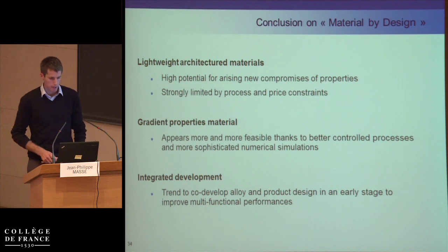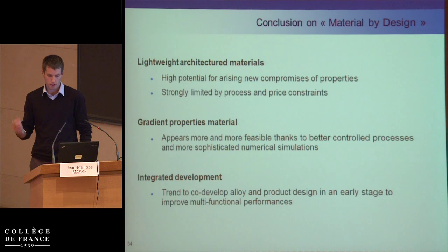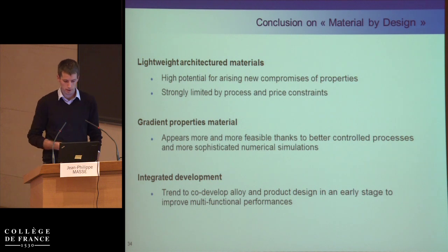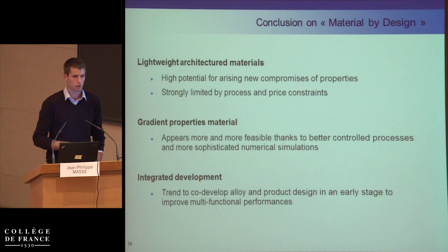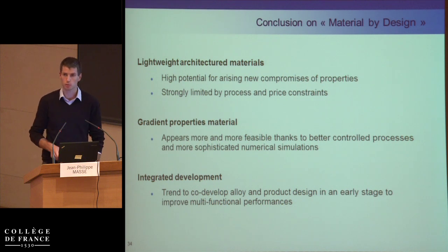So my conclusion on lightweight architectured materials is that we have a high potential arising to get no compromise between properties, but of course the limitation is the process, and also price constraints, because the few processes we have to produce such complex topology are really high in terms of price.